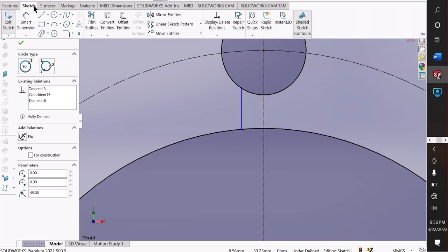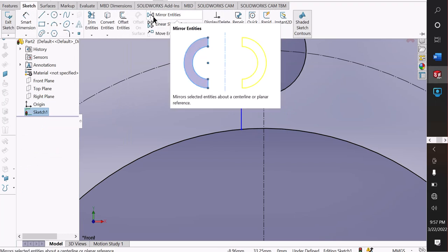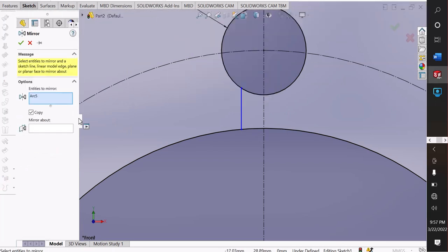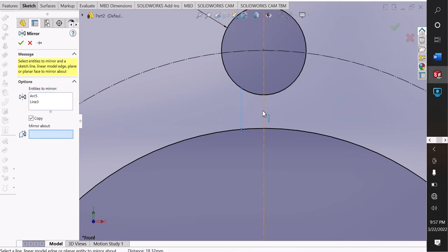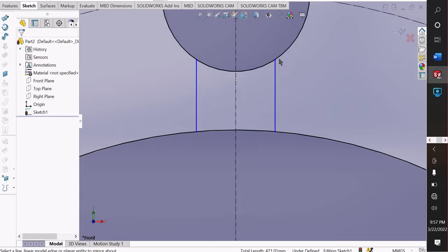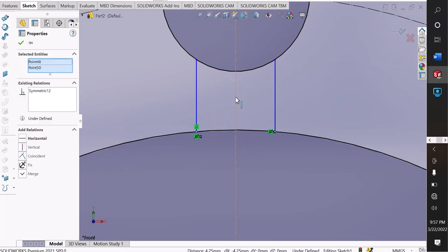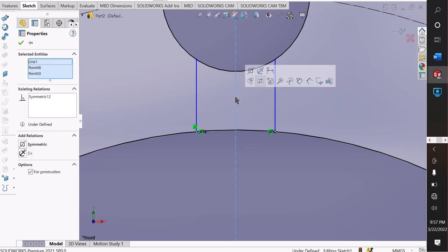Now I choose okay, mirror. First click mirror, mirror from center line, say it's mirror. Let's define. Here is one option first, select these two line points, first one, and hold control key this, and construction line, make sure it's symmetric.